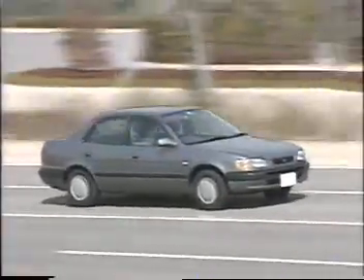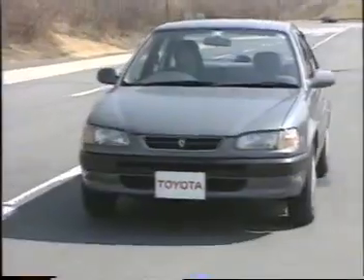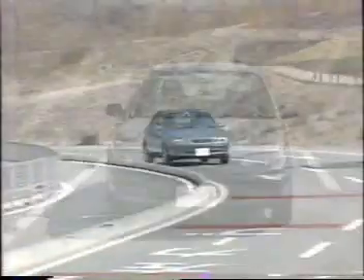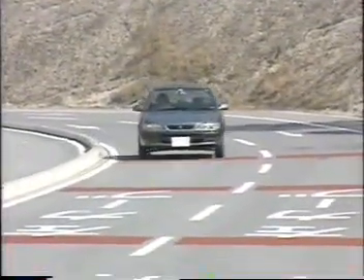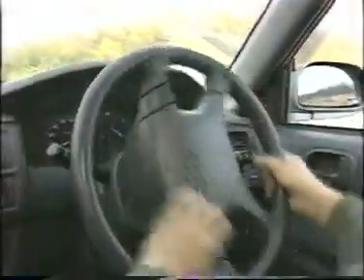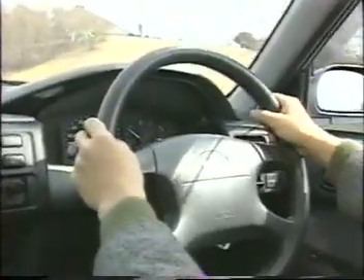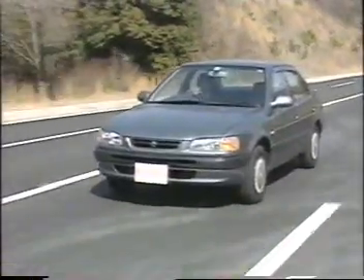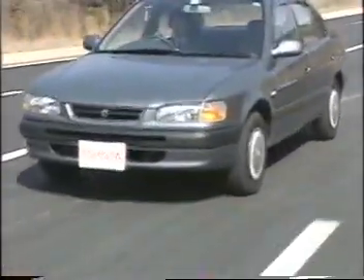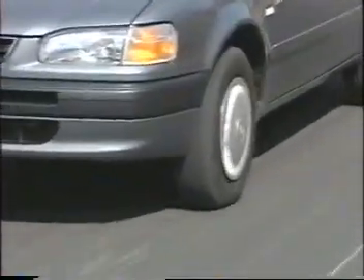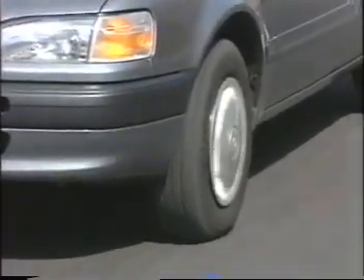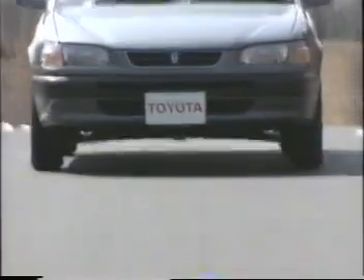A car has to be able to respond appropriately to various situations. It should provide a stable ride along a straight road, corner smoothly, and return safely and efficiently to a straight course after cornering. So wheels are fixed to the body of a car at certain angles to obtain the desired effects. The combination of these angles is called the wheel alignment.